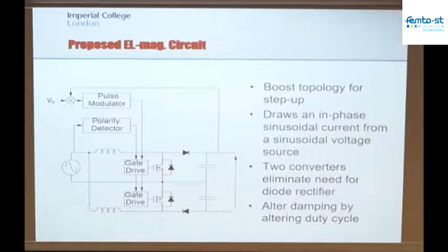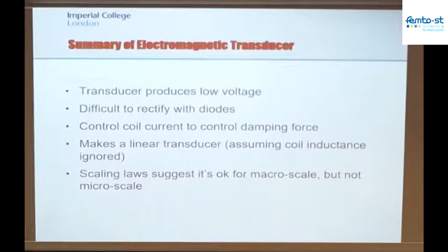Those are the 2 variables that we like to control in power electronics, because they're the things that alter fairly slowly. Voltage on a capacitor changes slowly, current in an inductor changes slowly. So they're the 2 things in power electronics you can control, and they fit very nicely into optimizing the behavior of a harvester, controlling the voltage on the output here to supply the load electronics, and controlling the current in the input inductors here to control the force on the harvester and maximize the power density.